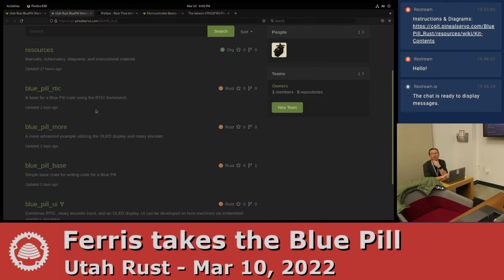You just take one. Resistance is more about ratio than it is about exact quantity for most considerations. So you don't need something that's exactly 200 or exactly 400. You can either put things in series with each other to add them together, or if you were told that you needed a 1K resistor and a 2K resistor, a 2K resistor and a 4K resistor would also work, depending on what direction things are going in.